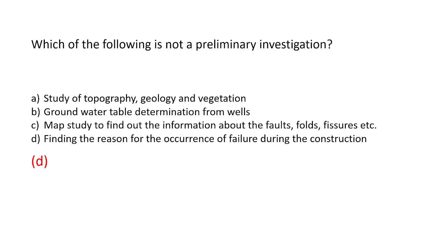There can be several reasons, right? Like there is some construction going on in the vicinity of the site that we are choosing. Because of the vibration, because of the pile driving there, we can have some failure here. Now, what do you think the main failure for any structure on the foundation is? It can be because of shearing failure, or it can be because of settlement failure. The settlement failure can be differential settlement, total settlement, whatever.